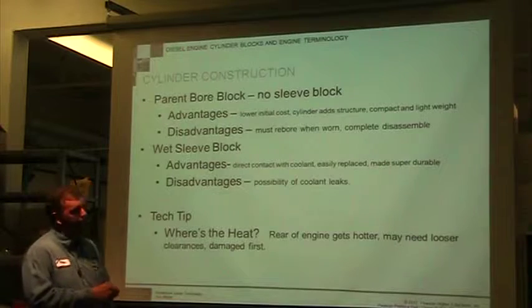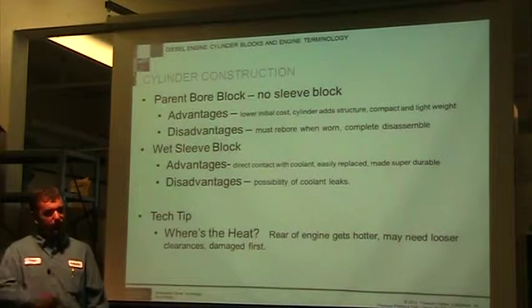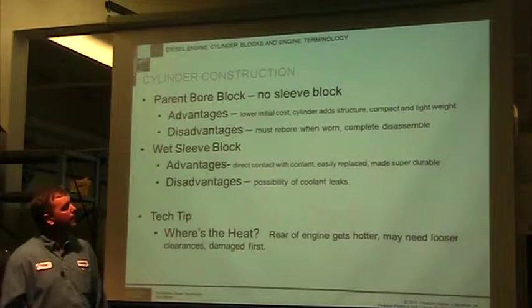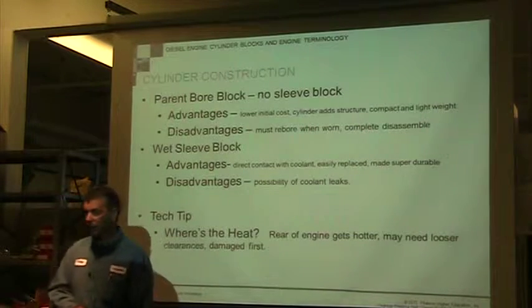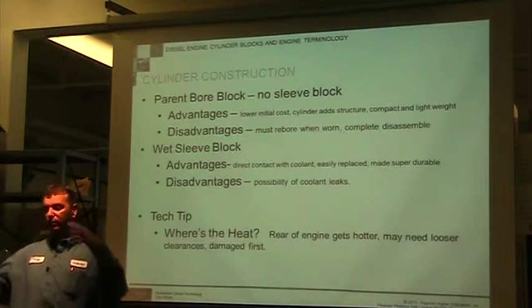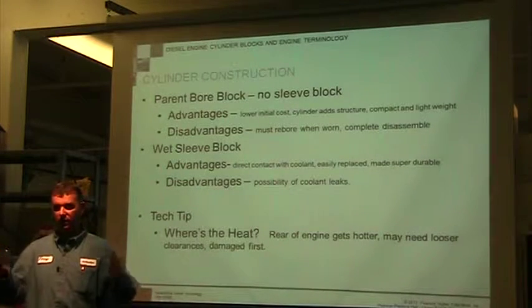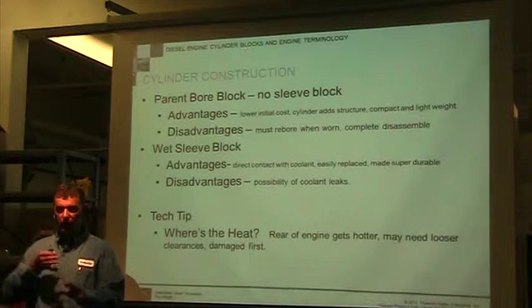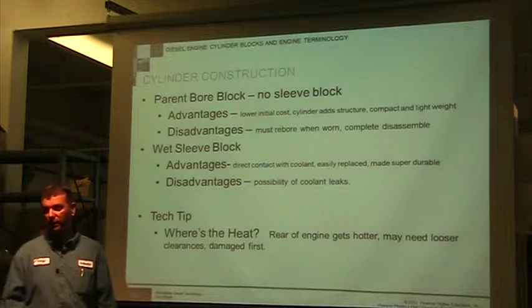Disadvantage, you have to rebore it. If it gets scored, you score the cylinder, you dirt it out, and it gets worn, you've got to rebore that engine. And to do a rebore, you have to completely disassemble it. And you can't just leave extra bolts and stuff hanging out. When they take it out and put it in their machine, they want that block as bare as possible so that they can actually put it in and bore that thing out. So it's a lot more time consuming when it comes time to rebuild it.